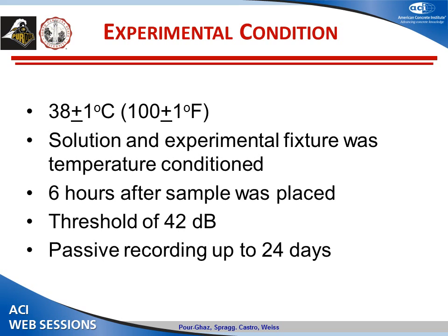And after we mounted the sample into the fixture, we let it sit for 6 hours. The threshold for acoustic emission was set at 42 decibels. This is mainly because we really don't want to hear anything from the chamber or from someone playing around in the lab. And we are measuring passive acoustic emission, really listening to the cracking and the wave propagation resulting from that, for up to 24 days.